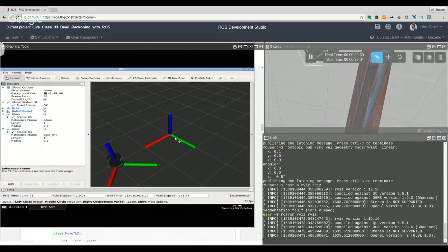So the use of the frames, if you want to dedicate yourself to robotics, that's very important. You have to really understand. So this is a simple example here for navigation, but there are other cases like the base link relation with the sensors and data detected. So, well, that's a matter for another live class. So here we have the odometry frame and the base of the robot, the center of the robot. So the position of the center of this robot is measured from that point there.